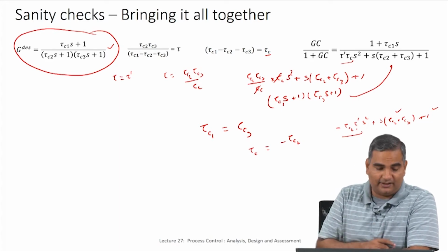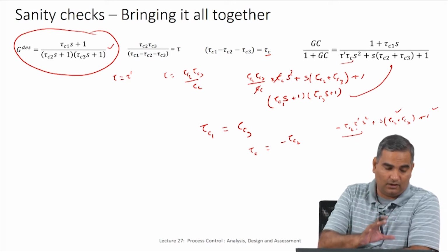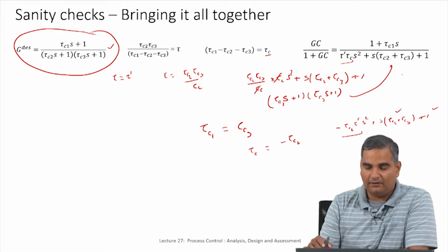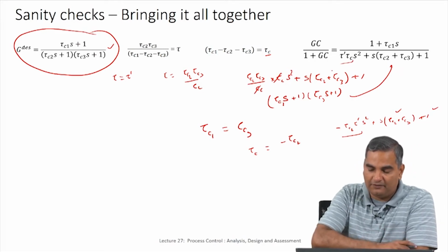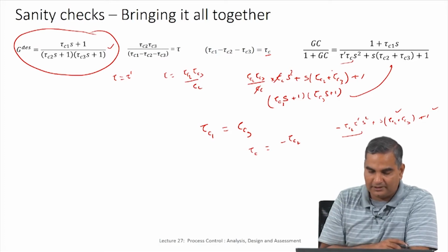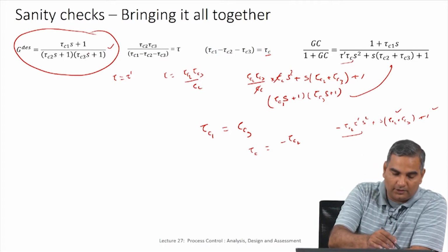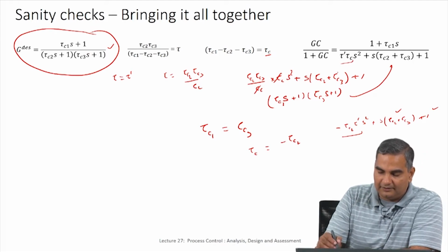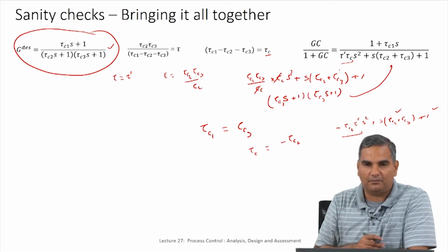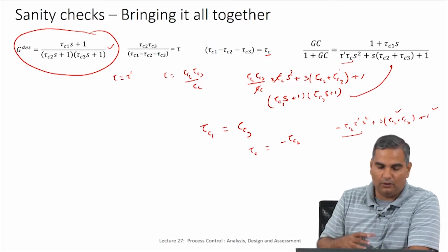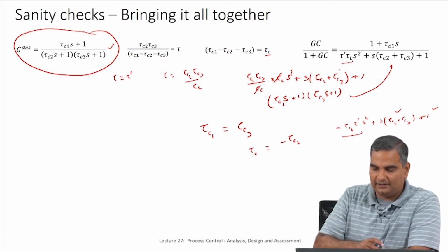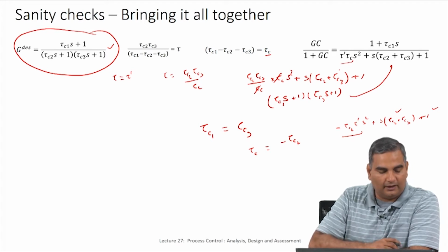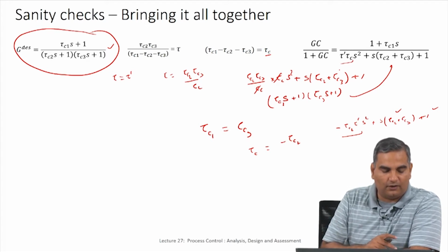So, this beautifully illustrates that while you have this G desired, as long as these two are not the same terms, the system will be stable even when you have process model mismatch, but the minute you make these two terms the same, if I had a process model mismatch, immediately I will get a negative here. Okay. So, even a slight process model mismatch will lead to problems. Okay. So, it seems to make sense in terms of all of these ideas coming together in this example of controller design for unstable systems.